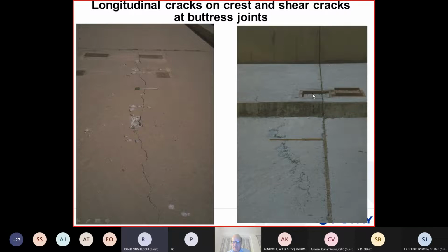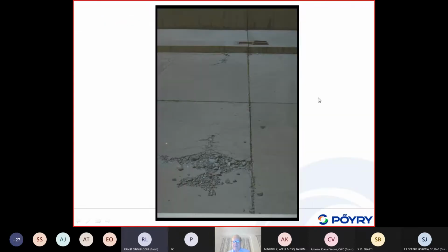So it was possible to measure in a simple way by these bolts the relative displacement of these adjacent blocks along all blocks. We see here some more. This is another one. This again is a joint meter. We see here some cracks. This is a crack in the top of a dam, which is an indication, as I said, of the large stresses in the across river direction. Usually, if you do the analysis, you do the analysis only for this kind of blocks in this direction.